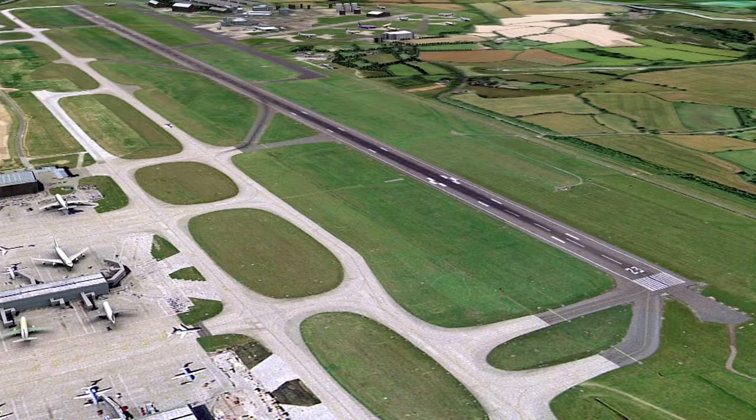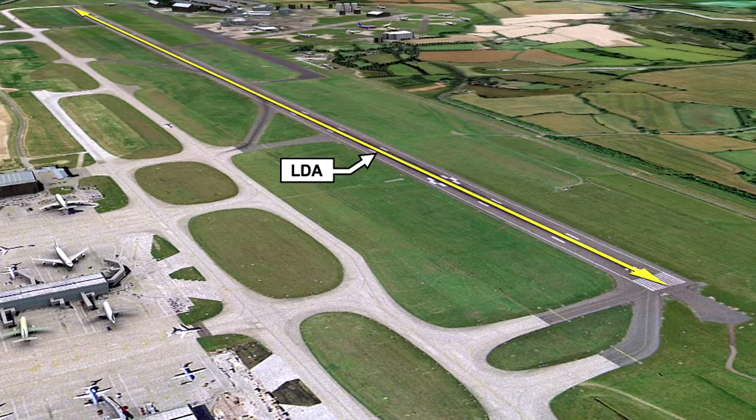The last of the specific distances we need to mention is the landing distance available, or LDA. The landing distance available is the length of runway which is declared available by the appropriate authority, commencing from the point on the surface of the aerodrome above which the aeroplane can commence its landing run, and extending to the nearest point in the direction of landing, beyond which the surface of the aerodrome is incapable of bearing the weight of the aeroplane under normal operating conditions.